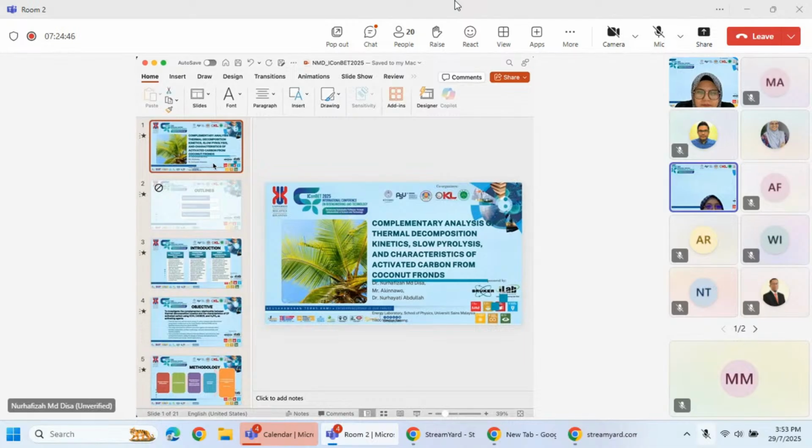From our research, we found that a temperature of 500 to 550 for woody plantation waste is appropriate to get biochar of around 60 to 70%, because it depends on the type of the biomass.